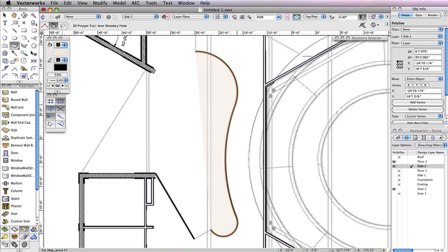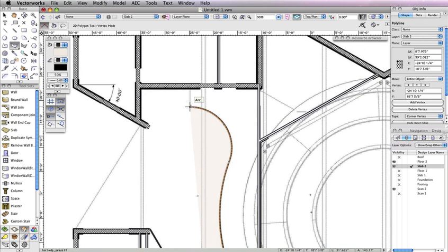You can now switch to the Polygon tool in the basic tool palette to finish creating the rest of the floor profile. Also, enable the first mode, Polygon from Vertices mode. Click at the topmost endpoint of the polyline you just created, and hold the Shift key while moving your cursor upward. Then, double-click on the inside face of the first wall you reach.